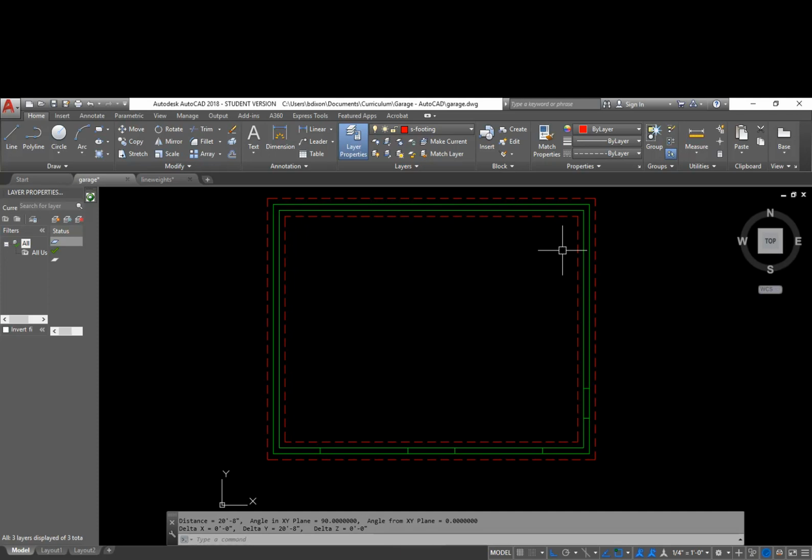Those are cut joints that basically, if the concrete starts cracking, they're either going to crack right at those joints, or if they start cracking, they're going to stop at those joints. So it's a way of predicting where or forcing the concrete to crack in certain locations, and then we can put caulking in it so that you don't end up with a crack that runs from one corner to the other.